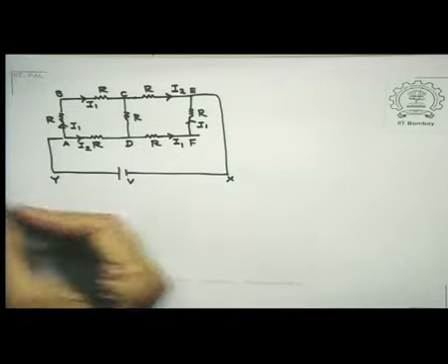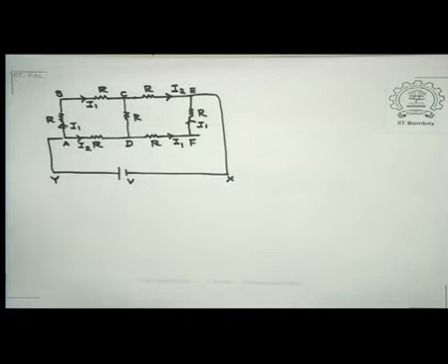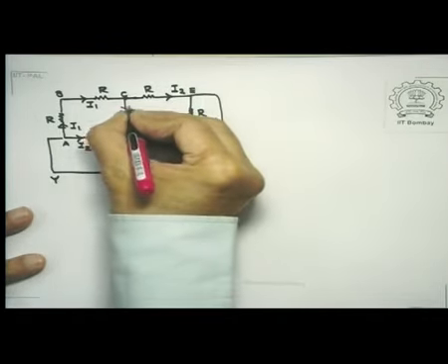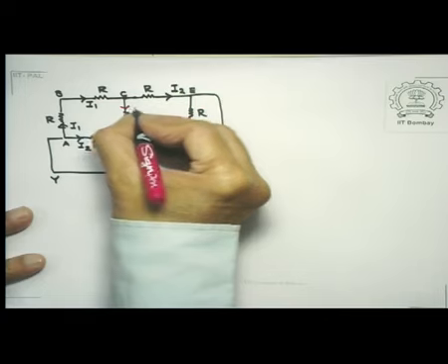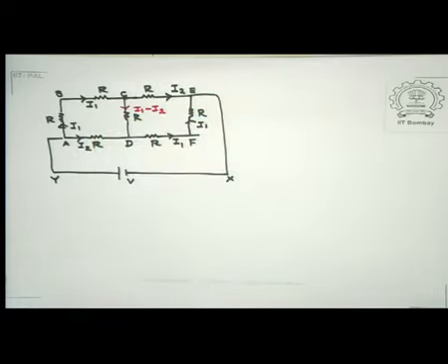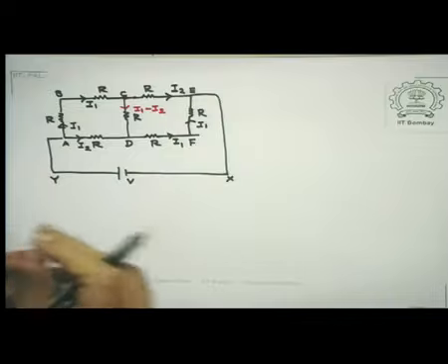Now let's look at the junction rule at the point C. So here I have a current I3 which is equal to I1 minus I2. So basically you notice that by use of symmetry, I have reduced the number of unknowns to only two, I1 and I2. So let's look at what we can say about I1 and I2.